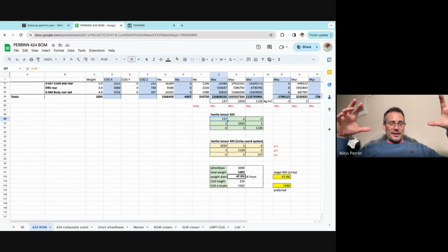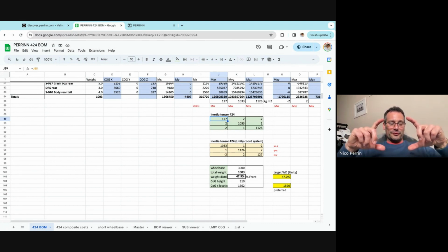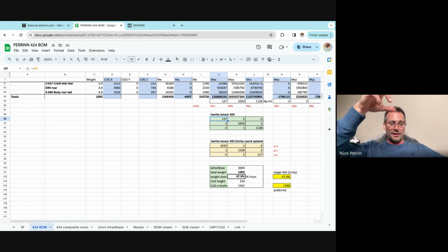The biggest effects are from the tire and the wheel, because that's a fairly big mass to rotate. But the other one is the electric motor. Even though it's quite small, it's going through a gear ratio of about 8:1, so its rotational inertia is multiplied twice by 8. So it's 8 times 8, 64 times the inertia of the motor. That's what is seen by the wheel.